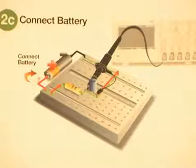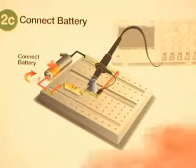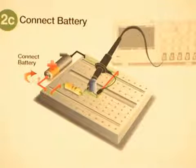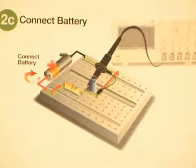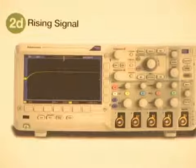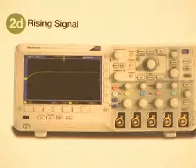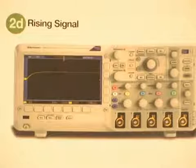Now, when we connect the battery and complete the circuit, you would expect the voltage to start at 0 volts and then rise as the capacitor is charged until it reaches 1.5 volts. And if you have a correctly configured oscilloscope connected, that's exactly what you would see. And it would look something like this. You can see how it starts at 0 and goes up to 1.5 volts. Now, this signal is pretty stable.